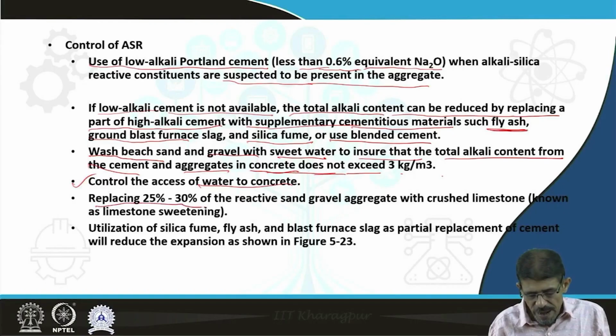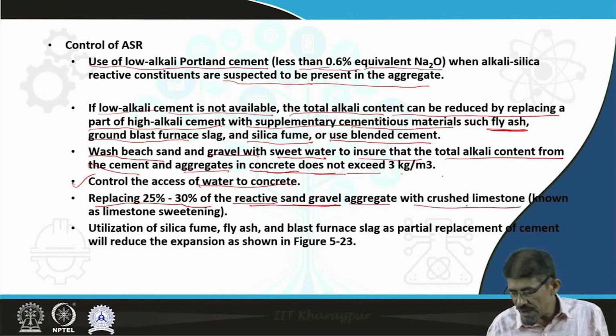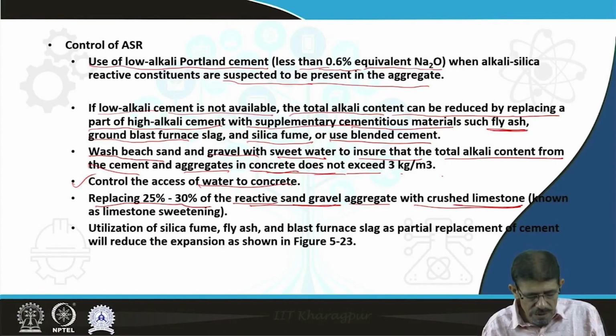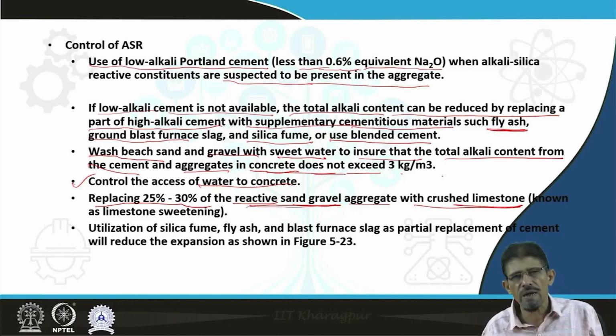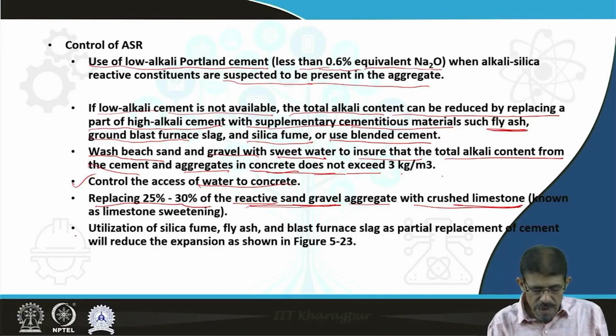Replacing 25 to 30% of the reactive sand gravel aggregate with crushed limestone is also known as limestone sweetening, or simply sweetening. The sweetening process is going to retard or control the ASR up to some level. Then there is utilization of silica fume, as we have already discussed.